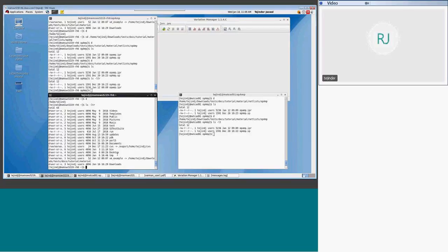Even if you're running 1,000 Monte Carlo simulations, in the end, if you see the report, it says effective simulations are like 200, depending on the parameter. So instead of running 1,000 or 10,000, or more, it's reducing the number of simulations while giving similar accuracy. Everything in design is about time to market, right? So you spend less time on simulation, you can do other things, and you still have confidence level.